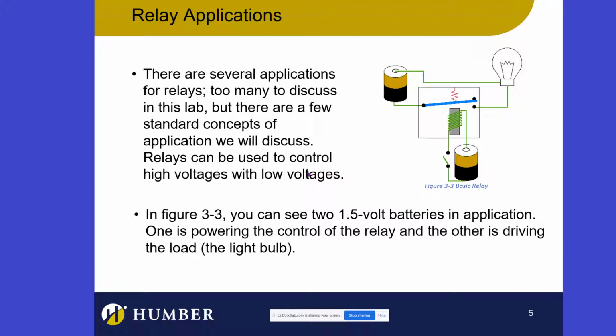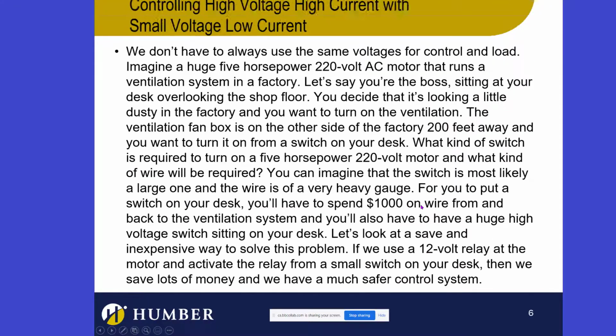So I use the doorbell to run this coil. And then this coil is going to change the contact here, and a lot of current can go through here, and then this would be my big motor that runs some big bell or something. So that's what's going on. So relay is just amazing. So let's just take a look at that.